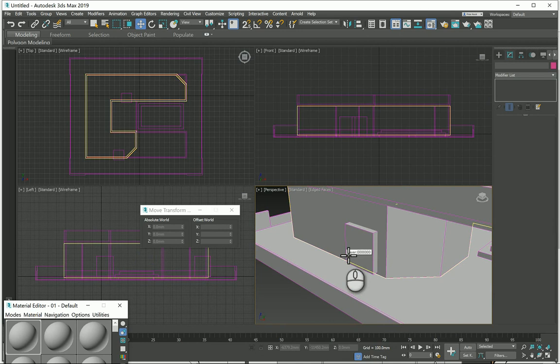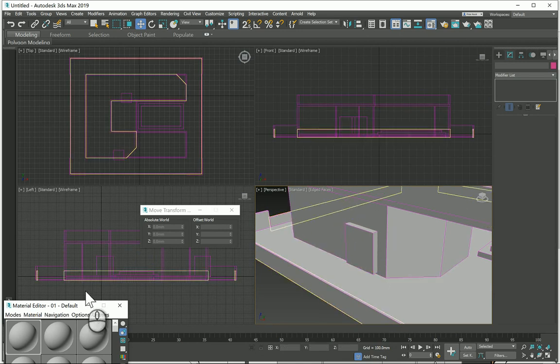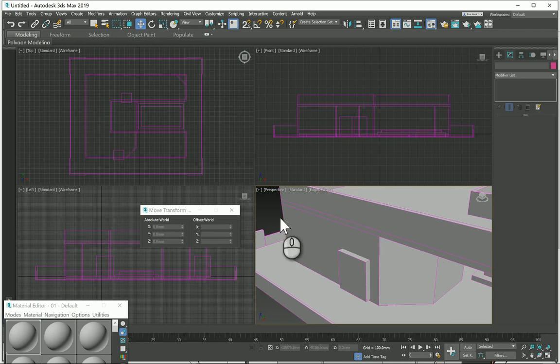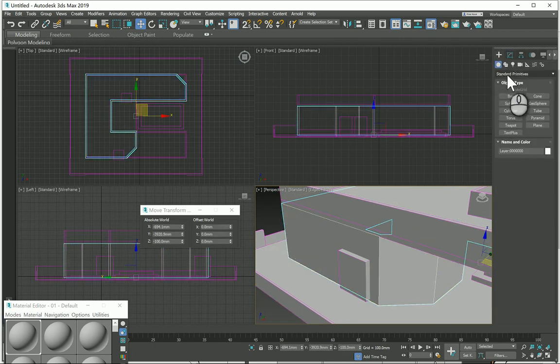That's the sub-object material. You don't want that. Just add the material and then do the Pro Boolean. Select and then go to the create, and then from the drop-down menu select the compound objects. And of course, you're going to find the Pro Boolean here.